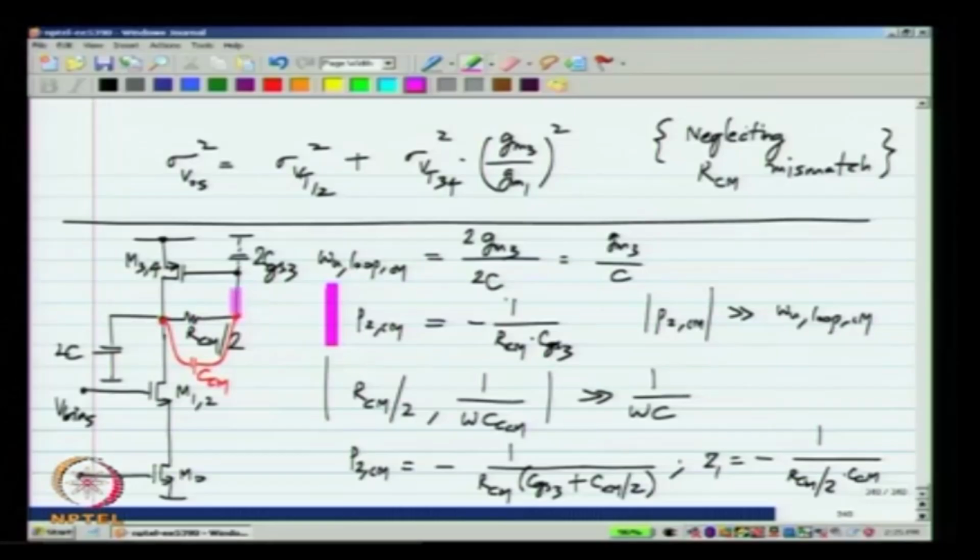We have seen circuits like this on other occasions, like when you calculate the frequency response of a common source amplifier, we have a similar circuit with a capacitance from the drain to ground, capacitance from the gate to ground, and a capacitance between gate and drain. And we know where the poles are in such a situation, there will be pole splitting and so on. Then we can calculate what the closed loop poles will be and whether the circuit is stable or not. A simple feedback circuit like this is almost guaranteed to be stable. You do not have to work too hard to make it stable or to eliminate ringing and things like that.